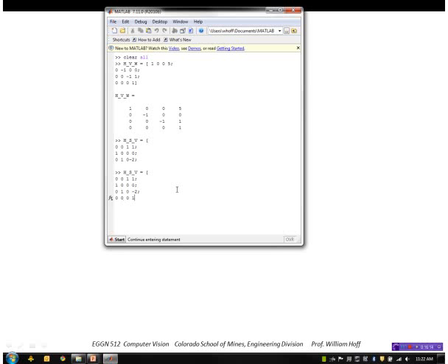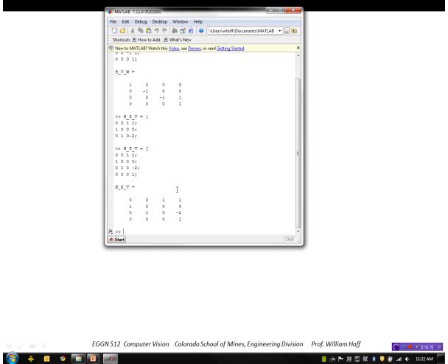Okay, so the position of the point in the world is the transformation matrix from vehicle to world times the transformation from sensor to vehicle times the position of the point in the sensor, which I said was 0, 4, 10, and then the 1.